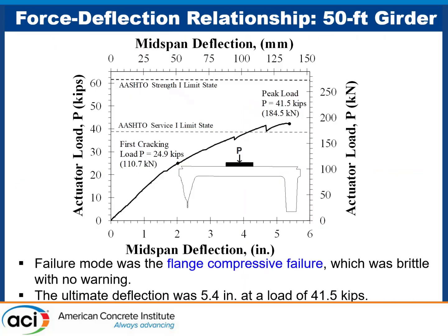And this graph is the best outcome of that girder testing. I have AASHTO service limit state line for this particular girder there, and I also have AASHTO Strength 1 limit state. This girder does not meet any of the AASHTO requirements. It was there, it was alive. People were walking on it, using it. Trucks were passing it every single day.